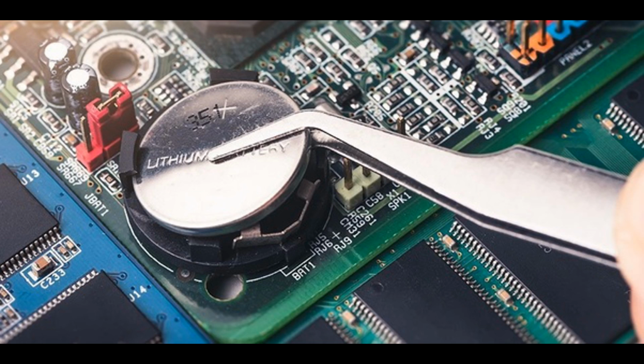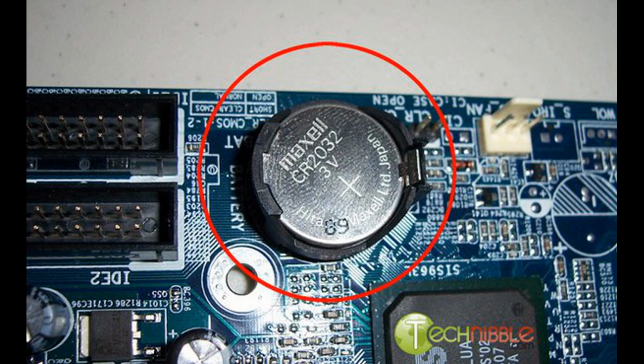Threshold voltage control. CMOS technology allows for precise control of the threshold voltage of transistors, which influences the voltage levels at which the transistors switch. By optimizing the threshold voltage levels, CMOS circuits can achieve lower voltage swing requirements for switching, reducing power consumption.